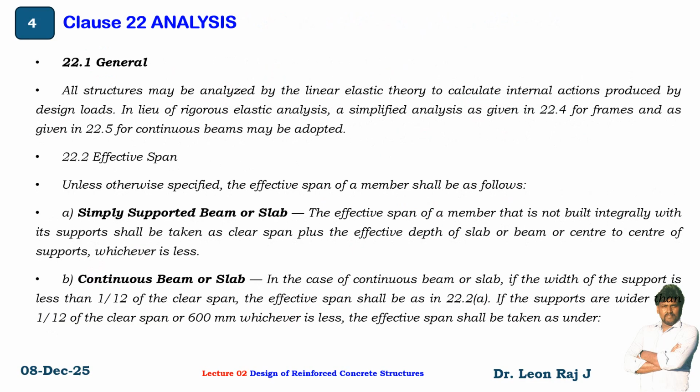Analysis, clause 22, 22.1 general: all structures may be analyzed by the linear elastic theory to calculate the internal actions produced by design loads in lieu of rigorous elastic analysis. Elastic analysis is rigorous and needs more complicated equations.